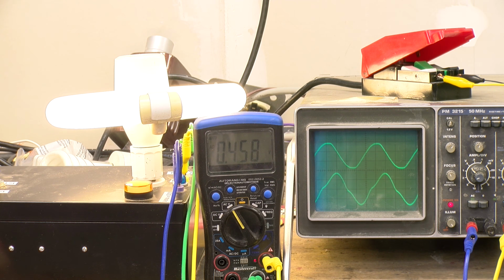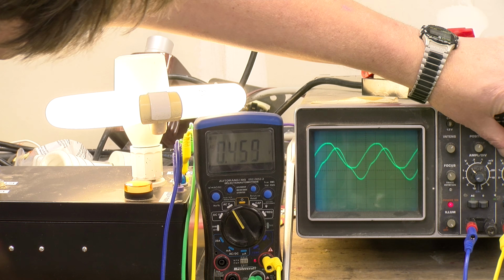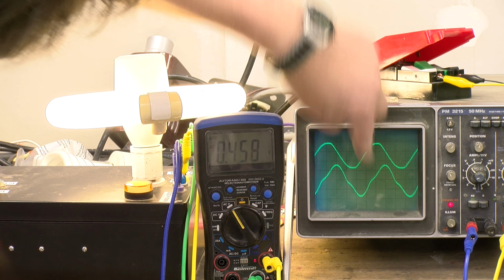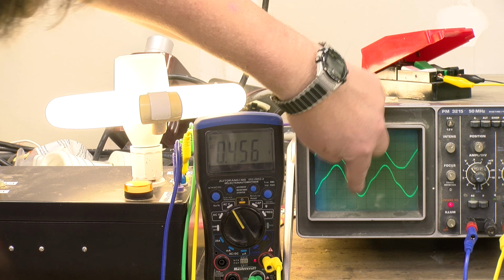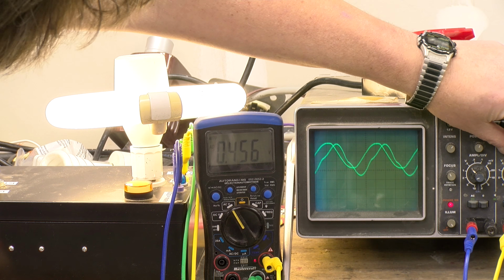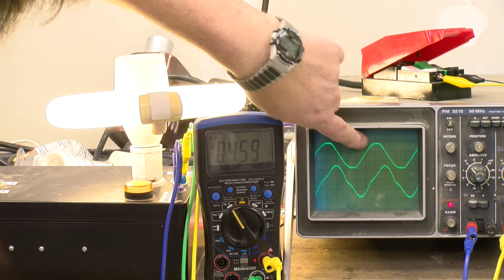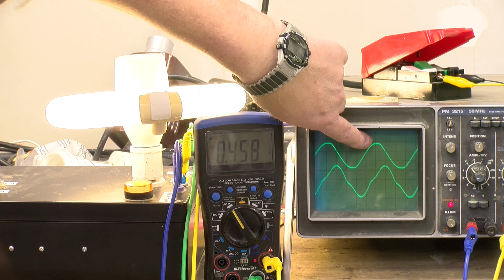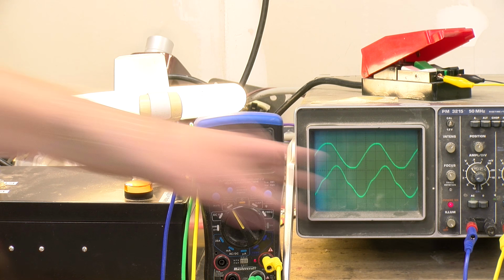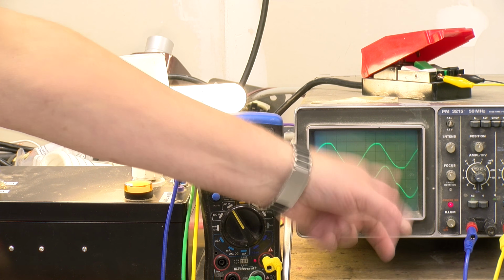That flicker is very typical, but look at that. The waveform, while not a perfect sine wave, is a little bit more triangular, so it has some harmonics, but it's basically very nice. It's lagging the AC voltage a bit. The current is lagging. What does that mean? It means it looks like there's an inductor in there, and indeed there is.